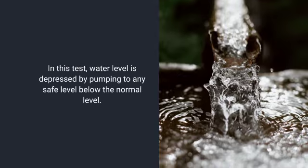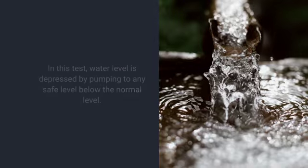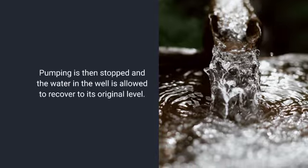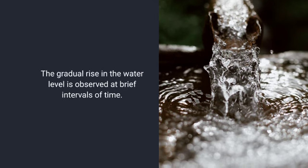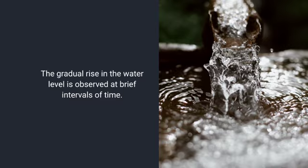Recuperation test. In this test, water level is depressed by pumping to any safe level below the normal level. Pumping is then stopped and the water in the well is allowed to recover to its original level. The gradual rise in the water level is observed at brief intervals of time.